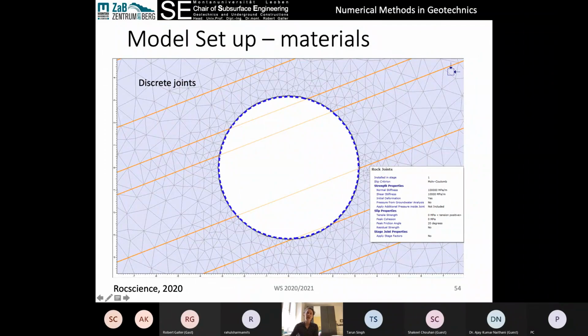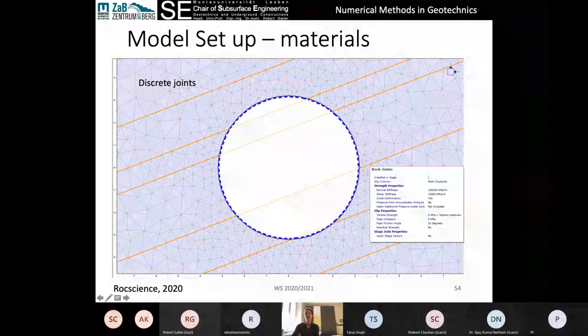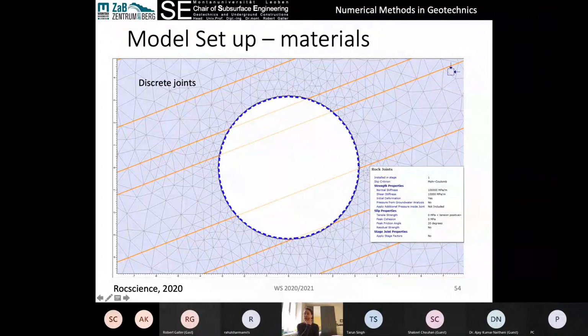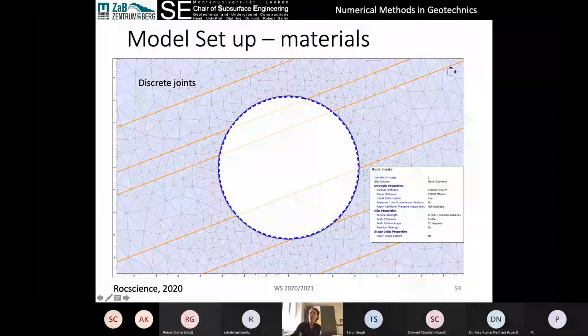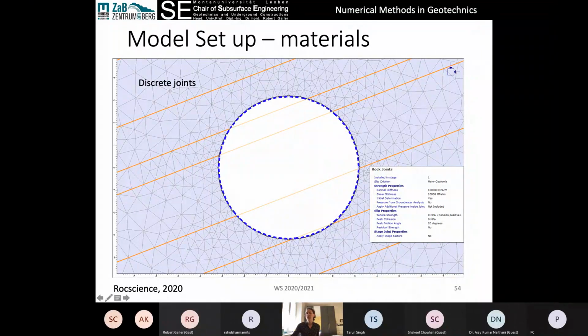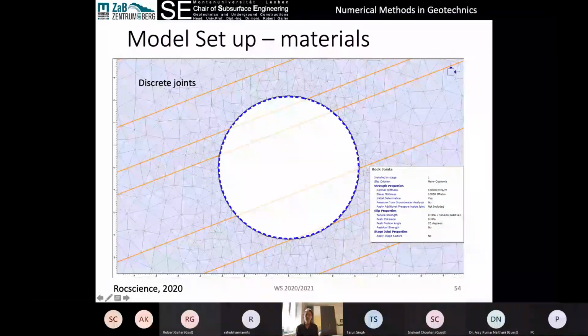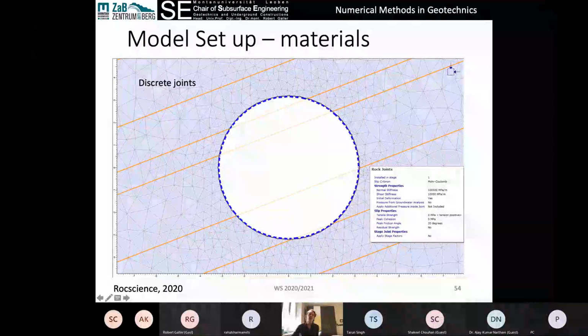And the level of detail then that we put to our geology depends on the scale of our model, the amount of detail that we're willing to compute for. So do we want to have very thin interbeds of siltstone in our sandstone here? Is that important? Is that an important component of the behavior that we think is going to happen? If so, then we should include them. If not, then we can sort of make an average continuum sandstone with siltstone interbeds, and we have to choose then how to represent that as Mohr-Coulomb or Hoek-Brown material. What sort of strength parameters do we put into there?